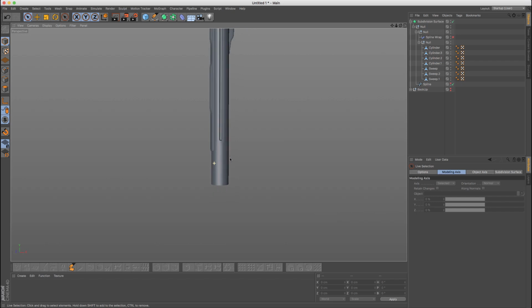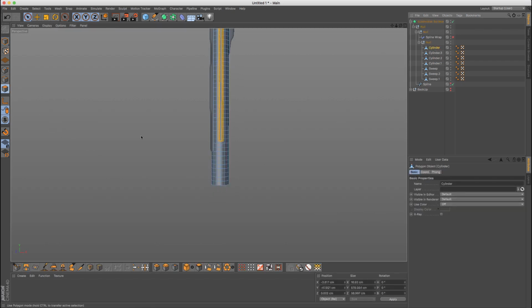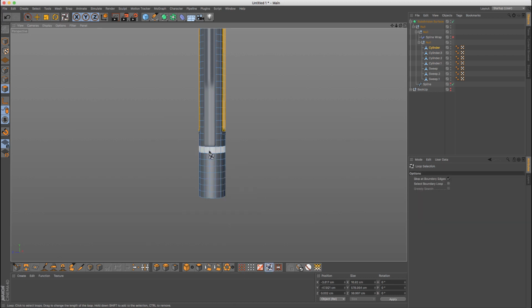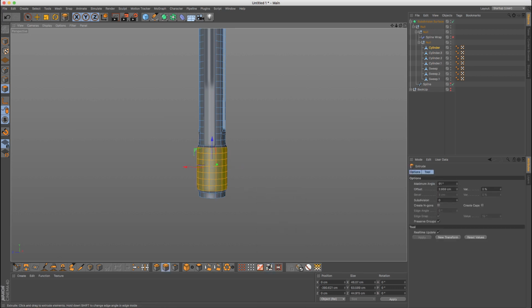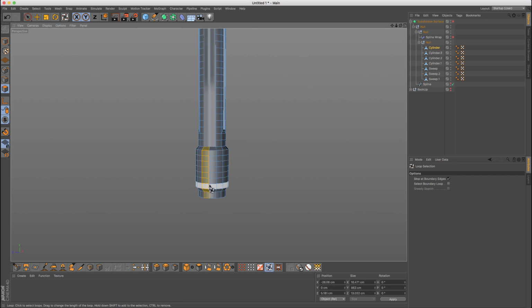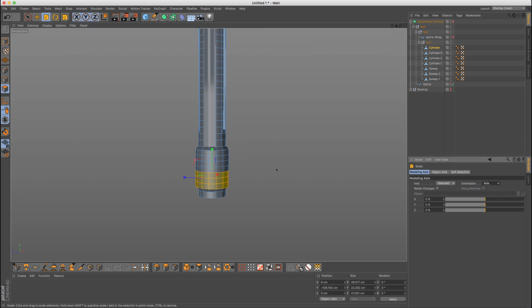And so let's come here at the very end, and what we can do is something similar to what we did before. So I'm gonna select this. I'm gonna use extrude, and I'm gonna use T for scale just to scale it down a bit, and then select this area and make sure I'm in axis mode and scale that up. Actually, yeah, we can scale that up.